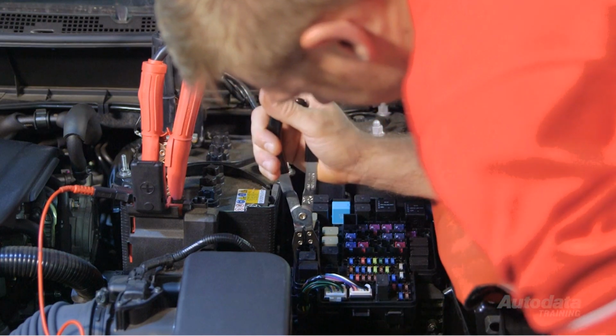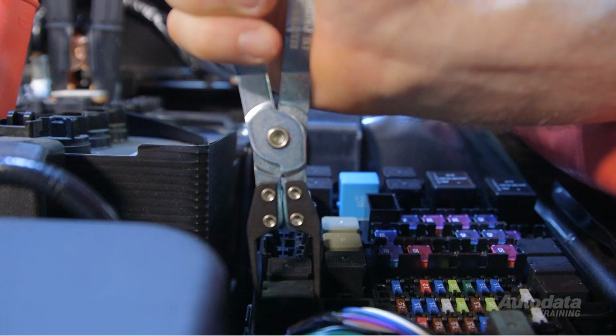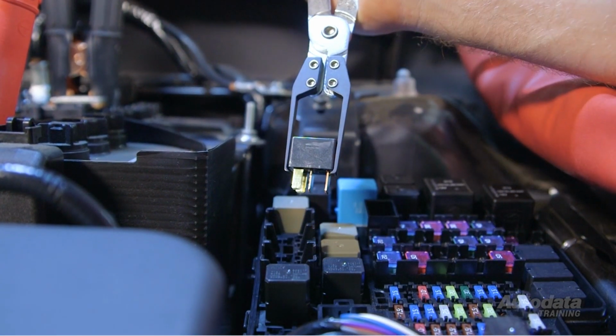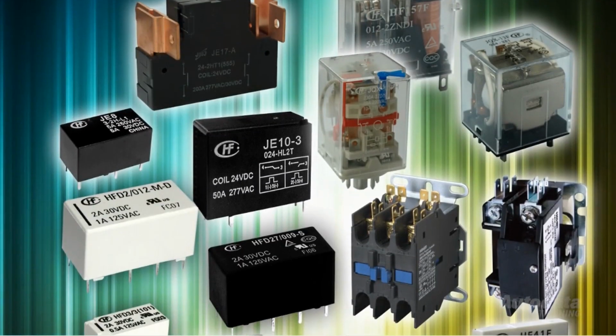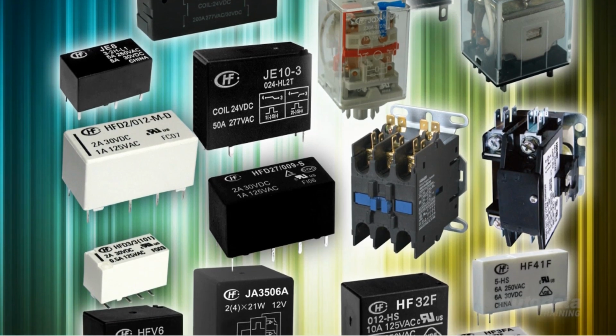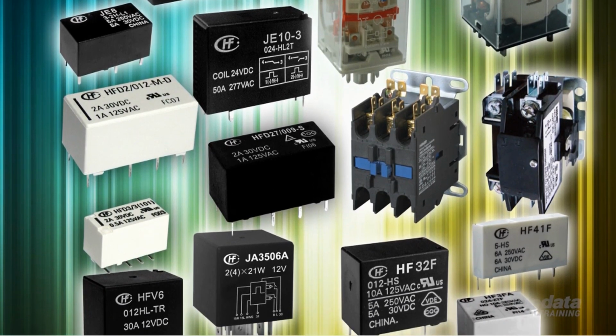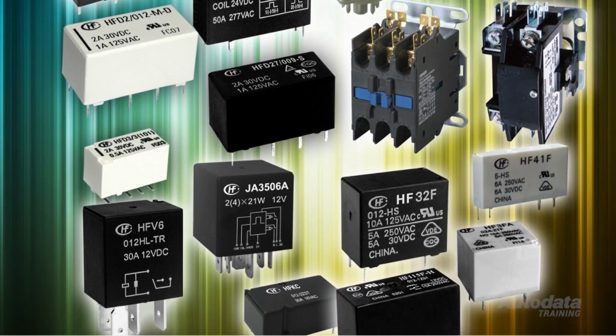When removing the relay, remember to use a pair of relay pliers. Failure to do so may result in spread terminals, causing more faults within the circuit. Not all relays have the same pin layout, so it's always good practice to consult the wiring schematic for the correct terminal location to avoid misdiagnosis.